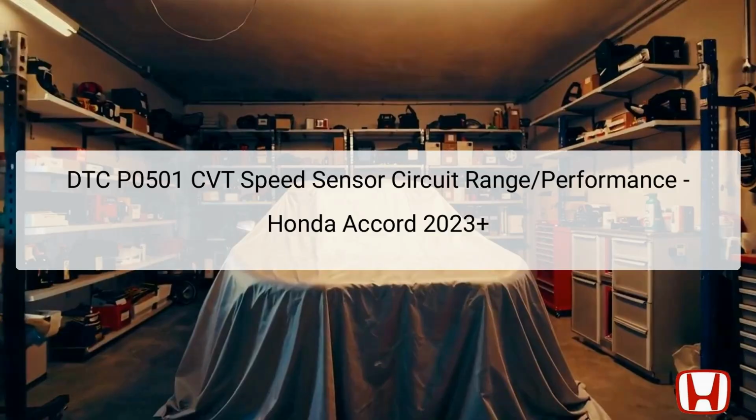The Diagnostic Trouble Code, DTC P0501, signifies a performance or range issue within the CVT speed sensor circuit. This code is particularly relevant to the Honda Accord models from 2023 and onwards, when the rotational speed ratio between the continuously variable transmission CVT speed sensor and the CVT drive pulley speed sensor is detected to be out of specifications. The Transmission Control Module, TCM, identifies this abnormality.